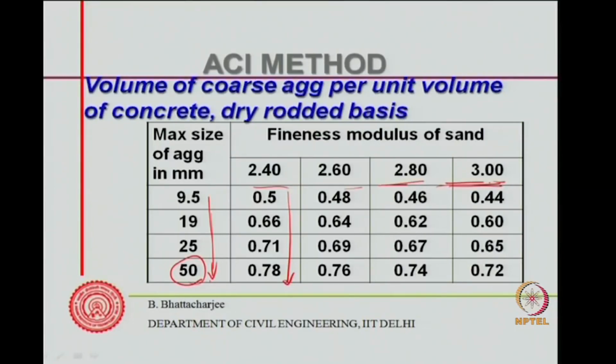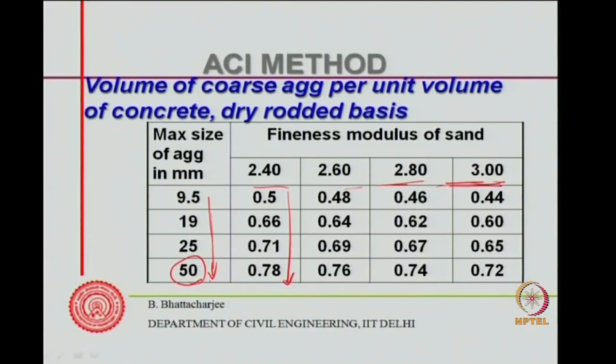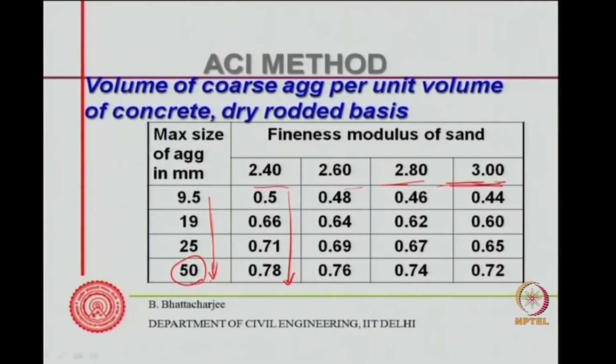Higher fineness modulus means coarser sizes, which means you have a better grading of the sand itself. Sands pack better, and more larger sizes are available in them.